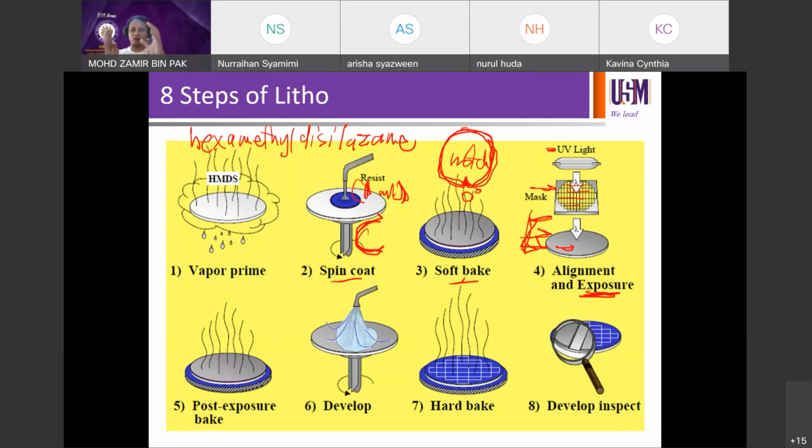It means when you print your current layer on top of previous layers, say in lithography one device probably has around 50 masking processes, depending on technology complexity. Say you already have previous layers that have run for half a month or so, and then you want to print the current layer on top of them. You want to make sure the current layer is perfectly aligned on the previous layers. If it's not perfectly aligned, you might end up with diagonal printing, with this theta.